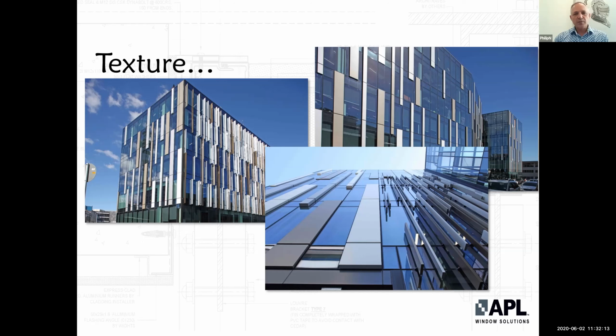Then a mechanical engineer will look at a facade like that and work out a percentile of how much of that facade you want to frit, which is like a shading system on the glass, or how you integrate a cladding system or a rain screen system to try and prevent overheating within the building itself.